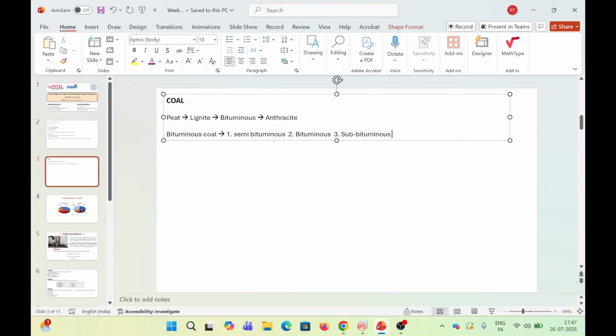When the carbon content is more, the amount of energy generated in the process is going to be higher. Similarly, if your sample has a lot of volatile matter as well as moisture, then that kind of coal will not give as much energy, or the efficiency with which the energy is produced is going to be low.